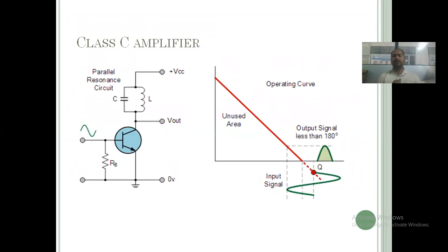See, we have seen another type of amplifier, that is the class C amplifier. Class C amplifier is the amplifier which operates for less than a half cycle, means whatever the output coming should be less than 180 degrees, right? Means if we apply a full signal, that is 0 to 360 degrees signal applied across your input, right? Then your output doesn't give all of the signal. It has a smaller signal, less than 180 degrees, coming across your output.